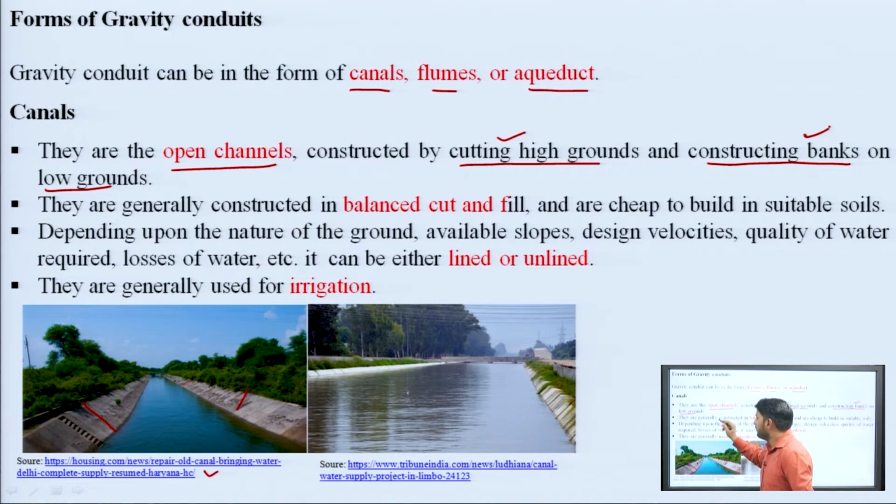So, what will be the best? They are generally constructed in a balanced cut and fill, meaning there should be equal proportions of cutting and filling, and that will result in an economical canal.